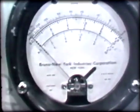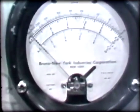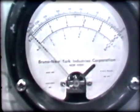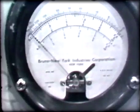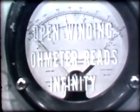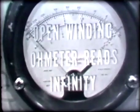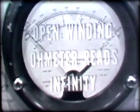If we'll take a look at the meter now, see that it reads infinity. Well, since the PSM6 always reads infinity for an open, this then indicates that the 150 turns winding, the one I'm now measuring, must be the open winding.